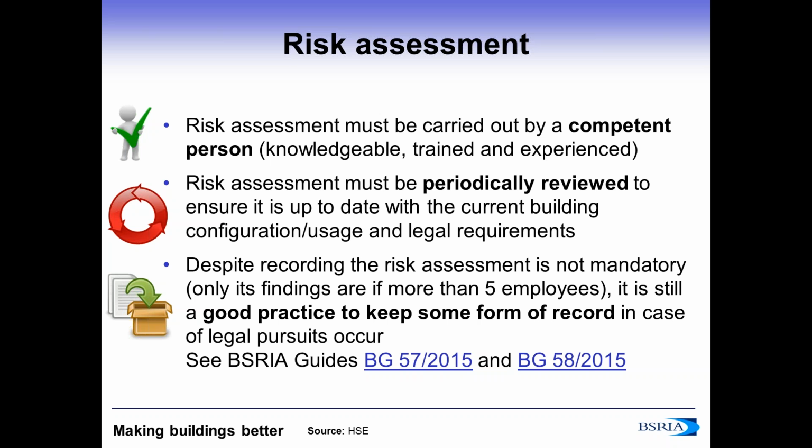A risk assessment is a snapshot of a system at a given time and therefore is valid only at this time. Any changes or modification to the building utilization, operation, water system configuration, or applicable legislation will require the risk assessment to be updated. Strangely enough, it's not mandated that a record of this risk assessment is kept. However, any findings or control measures to put in place must be recorded, and this is mandatory if your organization has more than 5 employees.